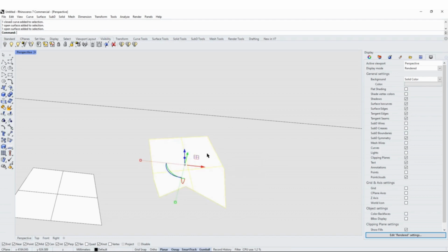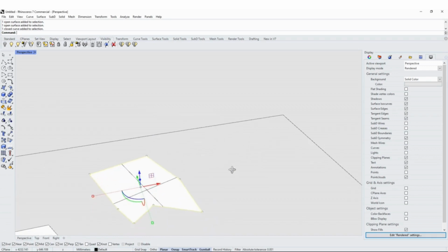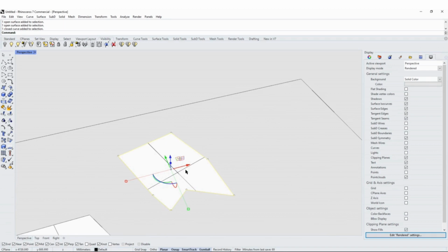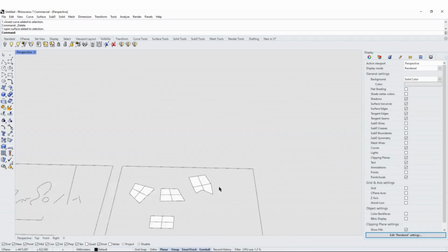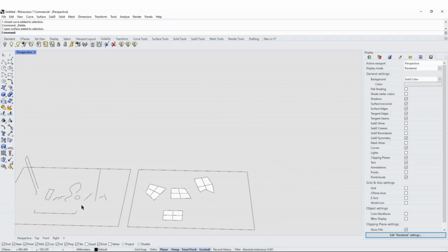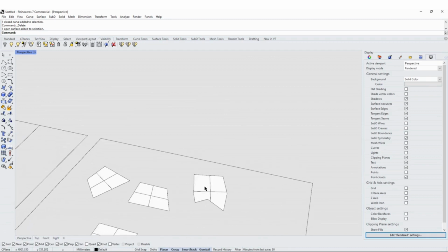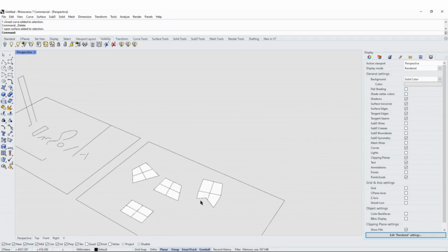If you're close to a point where there is more than one element, so for example here I have not only my original curve, but I have the surface that I created, you have a selection menu that can help you toggle between what you actually want to select. Let's say I want to select my original curve, the one that I created the surface from. I select it right now. I don't need it anymore, so I press delete, and right now I only have my surface that was created freeform. That's why we also put quite some time into understanding the curves, because now you know all the options from where you can define your points and from them create the surface that you actually need.